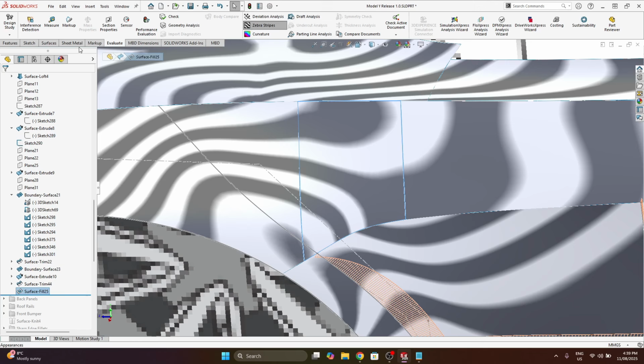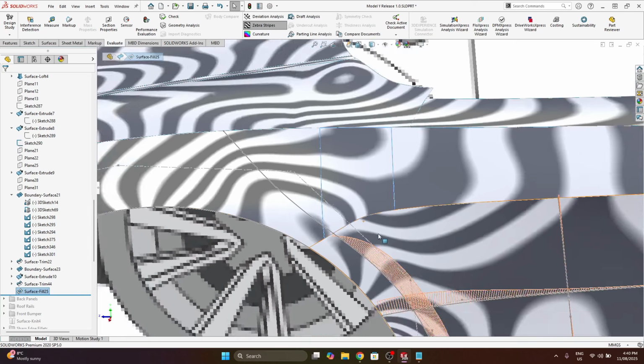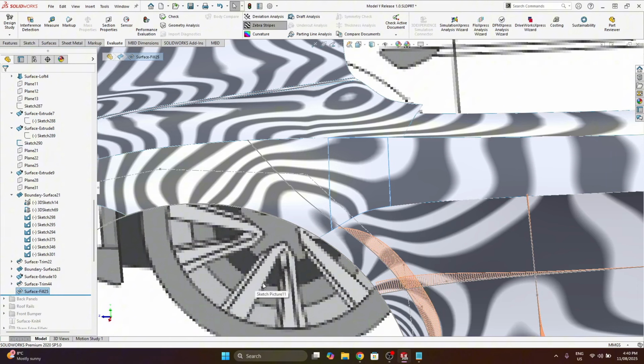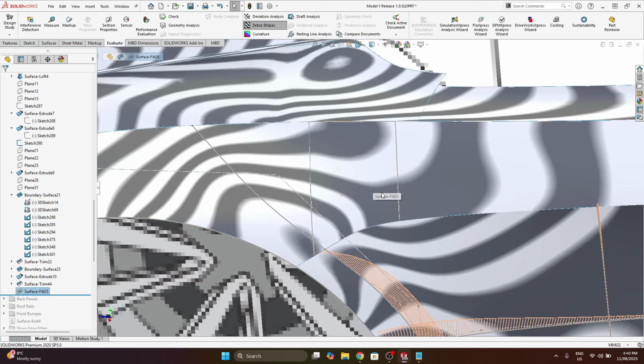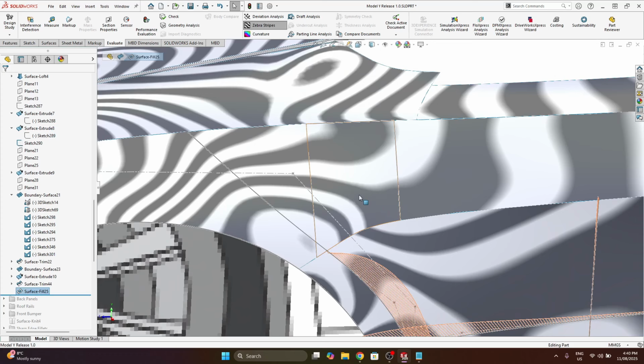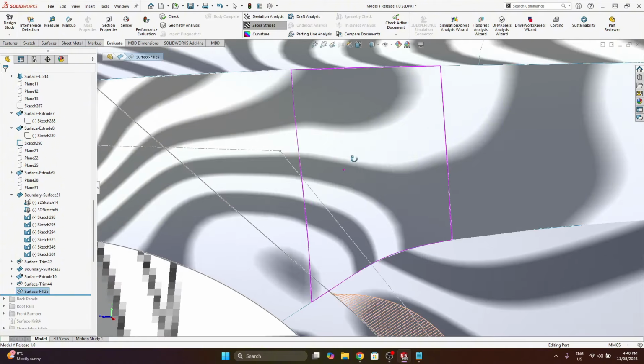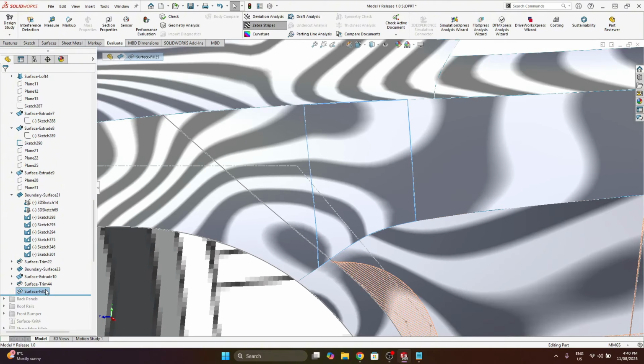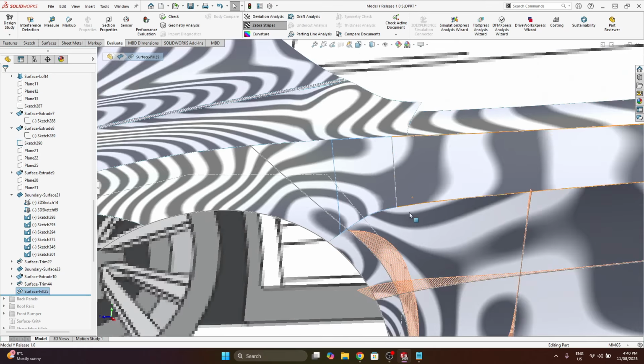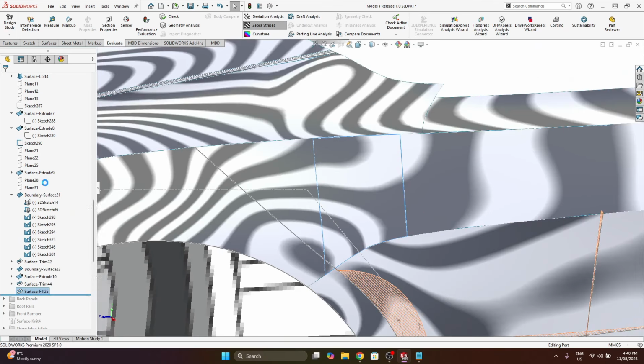The surface fill tool, it's kind of like a general purpose. You just specify a boundary and it fills it in nicely. And you can actually do that with a surface that isn't a distorted square or rectangle. It can have n number of sides. And internally what SolidWorks will do is build a nice NURB surface and trim it away. So it is really useful, but sometimes you just get really wonky results. I don't know if I'd say a gamble using it, but you don't have perfect control over your surface, but it is nice to use sometimes.